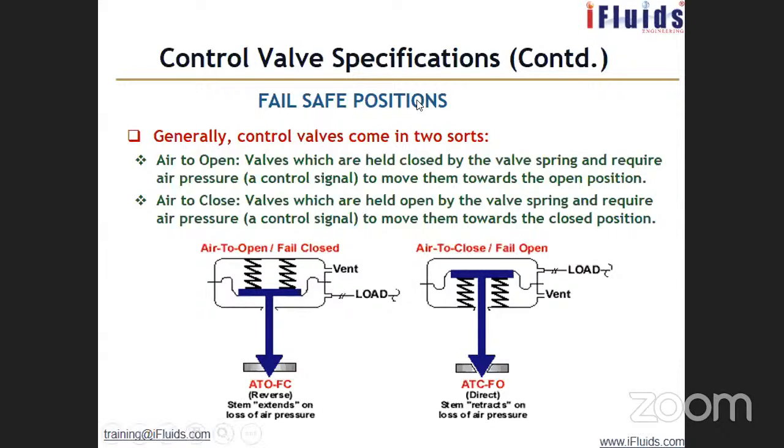Any questions? What is the difference between cavitation and flashing? Cavitation is when two-phase flow comes into the valve. It's something similar to what you have seen in a pump. When you pump a hot liquid at its boiling point, if the pressure drop in the pump reaches the vapor pressure, then the liquid vaporizes inside the pump casing. Similarly, here also, if the liquid starts vaporizing inside the valve, then it is called cavitation.